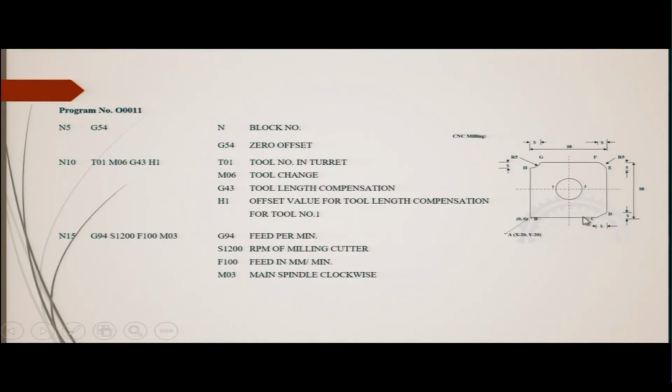So, these movements of the milling cutter are as far as the axis is concerned. That means this is the movement of the axis, and the periphery will be moving at the radius of the milling cutter. That much compensation we have to give for the movements that we are planning, so that at the periphery, away from the axis of the milling cutter, that much of the tool is compensated, that is, along the diameter.